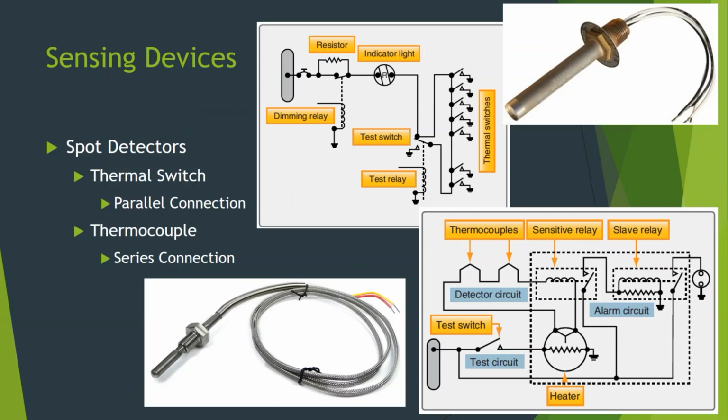Maybe the right wing overheat switches were like this, and the left wing overheat switches were like that. We'd get a message saying, hey, there's a stuck switch in the right wing. The wing is 40 feet long. There's 15 switches in it. And to get to them, you've got 3 panels. The outboard panel had 600 screws in it. The inboard panel had over 400 screws in it. And you've got to figure out, is it a thermal switch in the inboard panel or the outboard panel? Well, you better hope you choose right, because that's 400 to 600 screws. And if you choose wrong, it's 1,000 screws, right?